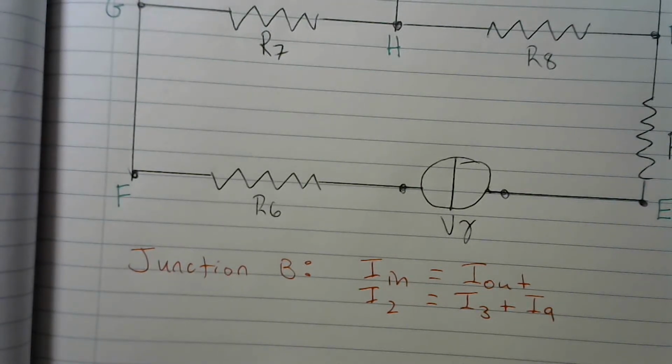And you would go around your circuit and identify all of the other points where there are 3 or more wires meeting, and using the conventional current and whether the current is flowing in or out of the junction, then you would use that to write the rest of your junction equations.